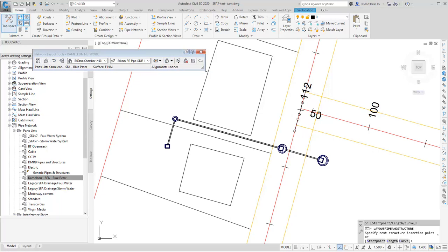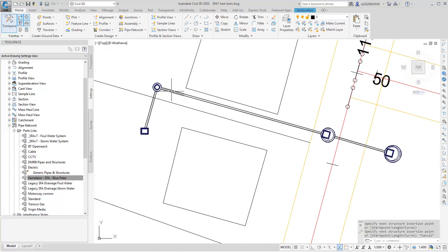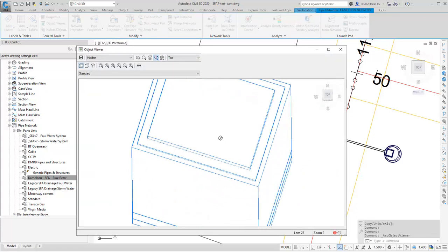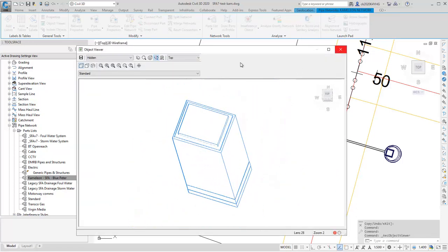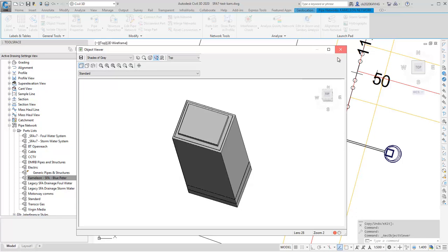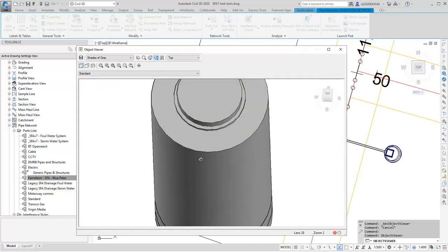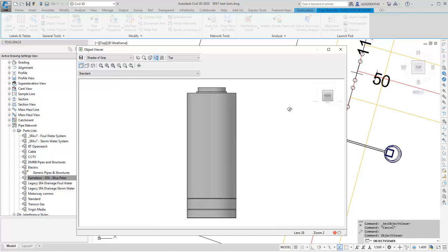At this stage you can see that the geometry is a lot more detailed than the part builder stuff. They were, after all, originally designed in Autodesk Inventor. Some useful additions have been added to this geometry. For instance, notice the grooves towards the bottom of each part. They represent the invert and the soffit of the maximum recommended nominal pipe diameter for the structure from the SFA book.